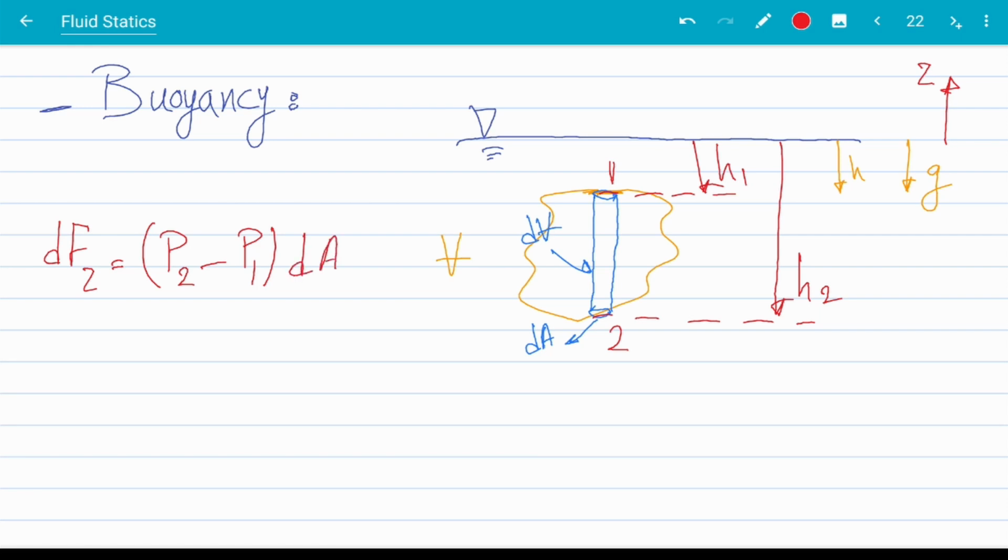Of course, you know that, let's say you have a cylinder, like this blue element, and you have submerged it into the liquid, and you want to know what forces are acting in the z direction, in the direction or the opposite direction of the gravitational acceleration. Now, you know that in a situation where we're dealing with a hydrostatic fluid, the only surface force acting on your fluid element is the pressure. That's why I know that it will be P2 minus P1 times dA.